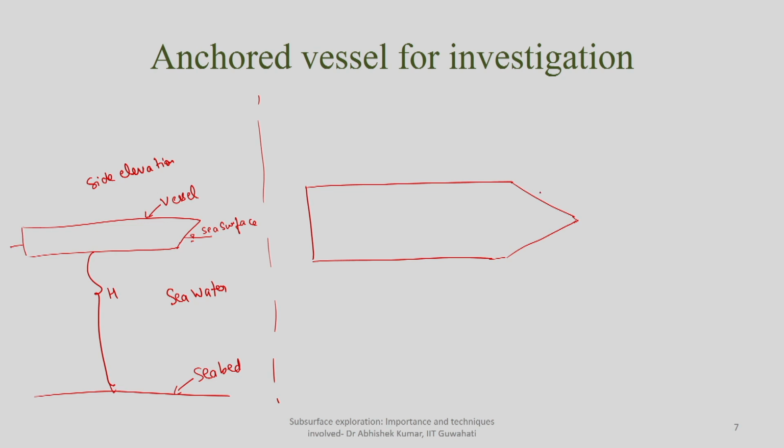What I meant to say is, whenever you are lowering some kind of assembly for sampling from here, this vessel should not move in any lateral direction, even perpendicular to this. So, there will not be any movement in this direction or in this direction. In order to ensure this, generally you go with anchoring this vessel.